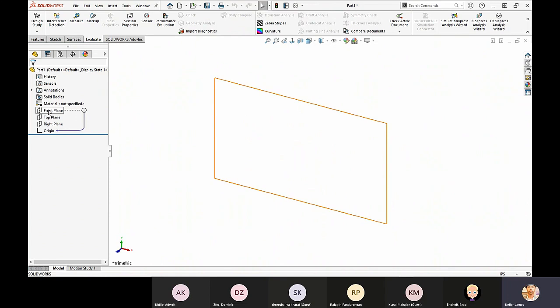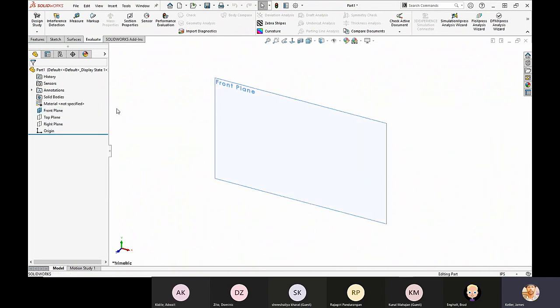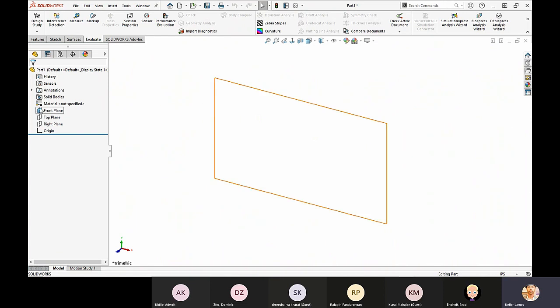They're hidden by default. If you want to right-click any one of them and choose the icon here at the top, the eye icon, to show or hide, that can be done no problem. Another thing, if you do that and you see that these icons here are colored instead of an outline, you can tell that they're shown, because sometimes over here, if this option, View Planes, is not toggled, you'll see it's set to show here, but I don't see it in the graphics area.